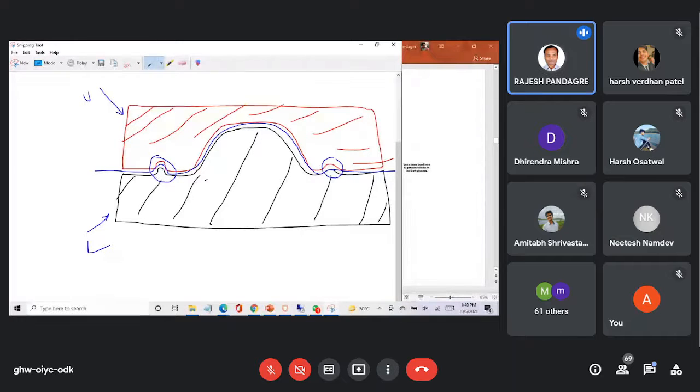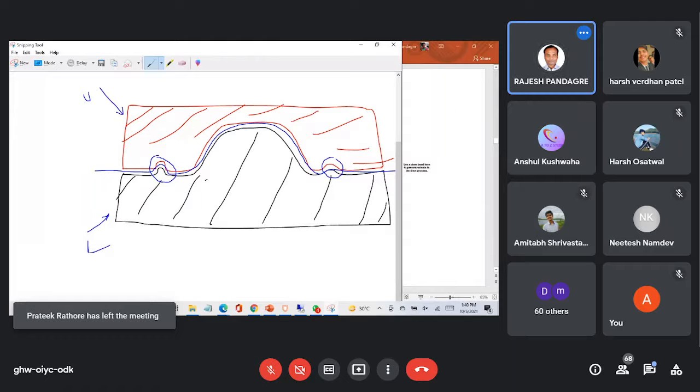What is this called basically? This is called draw bead. Okay, this is called draw bead. There are multiple names of it, and multiple functions of this. So we call it draw bead, or flow bead, or lock bead. This will help us to flow the material inside the die.